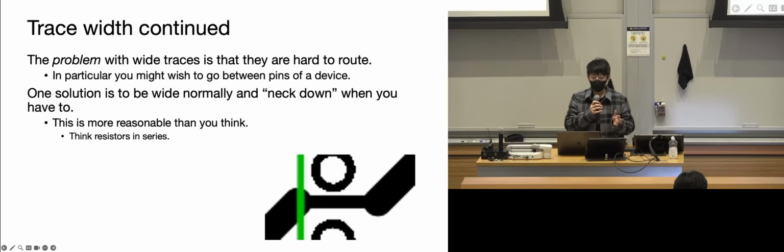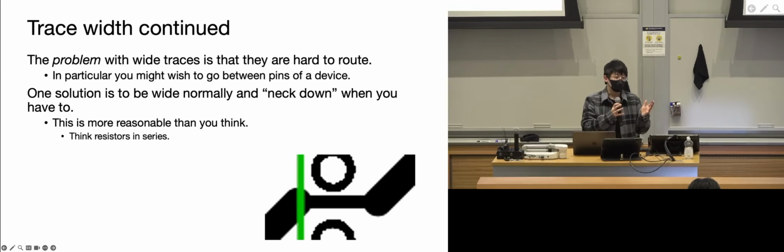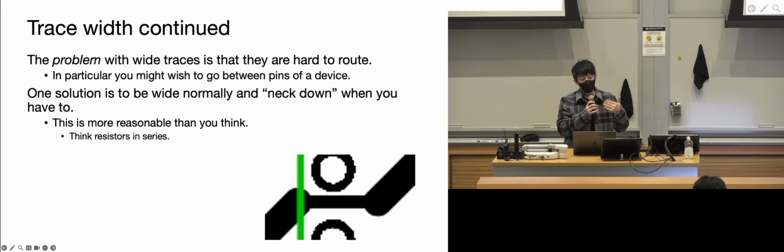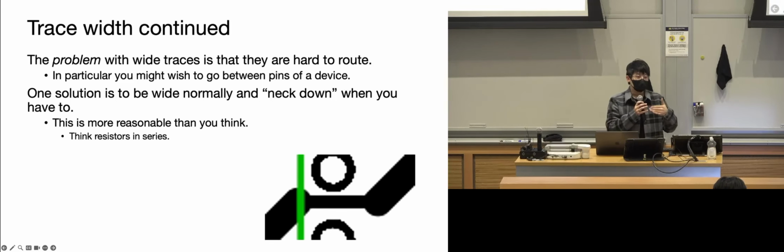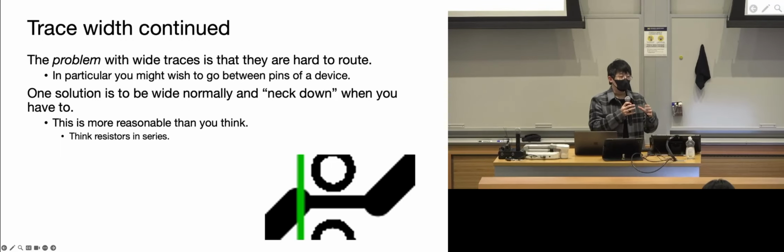For the beginning, for the first couple of boards you design, it's totally okay to just start with something large. But as you gradually get more practice, you will see there's a trade-off between the trace width and the overall integration of your device.